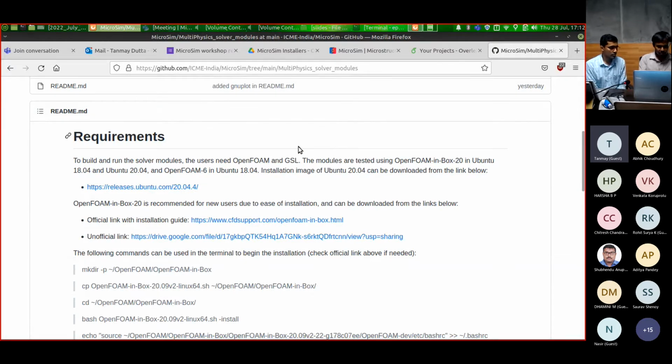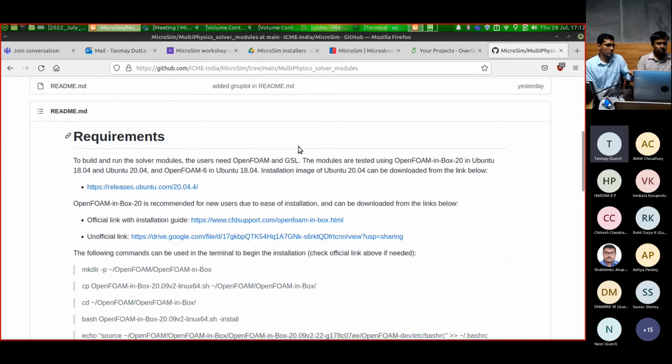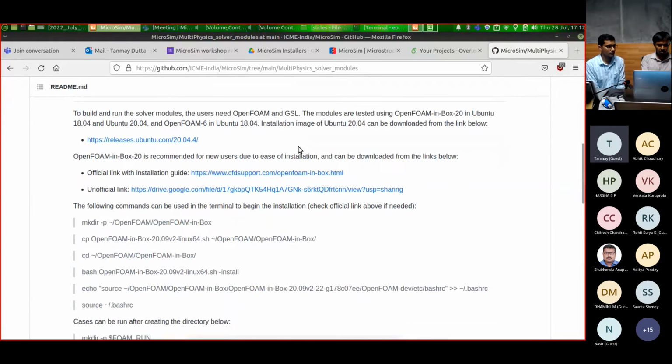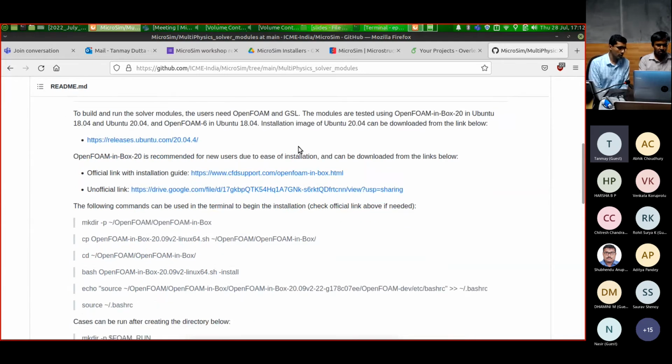So these solvers can be modified further for multi-step aging, where we can evolve the temperature stepwise. We can specify the temperature in that way. We will have the cooling for some time, then we can hold the temperature, and then after some time cool it further. So we can have multi-step aging processes, which can be extended with this model. Precipitate growth can be done like that. That can be one future release feature.